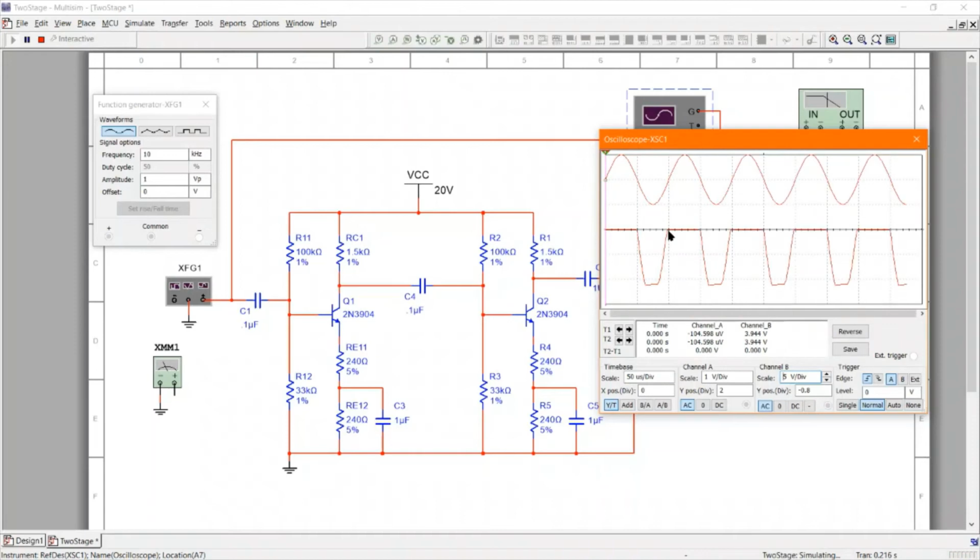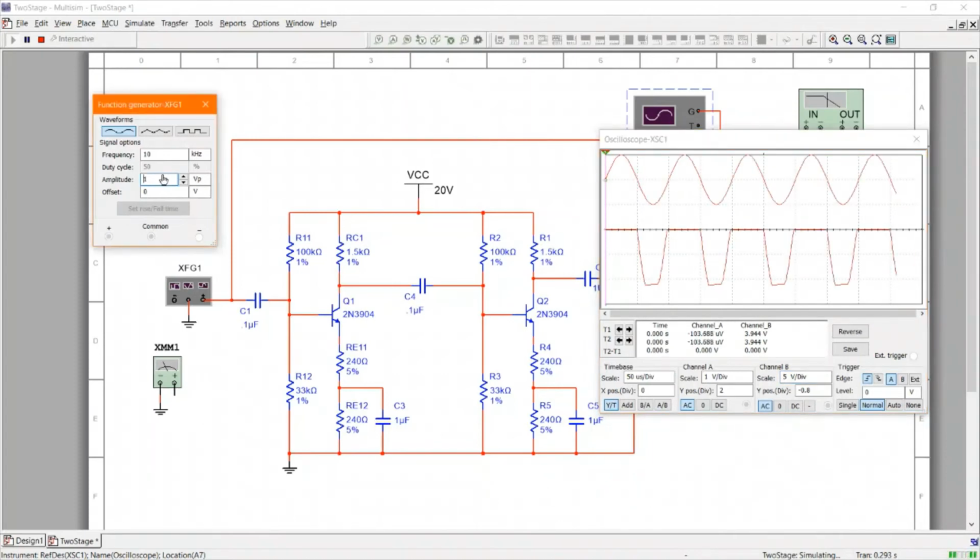And the reason you can't do that is because it actually wants to go higher. So you cannot compare the peak-to-peak input to the peak-to-peak output because it's not reaching that peak. So in order for this to work, you're going to have to reduce the input voltage until you get a sine wave on the input and the output. And you cannot measure gain properly unless you have a good output. If you got garbage coming out, then you're not doing a proper gain measurement.